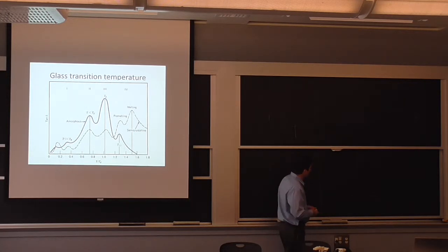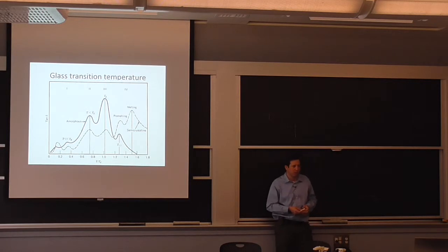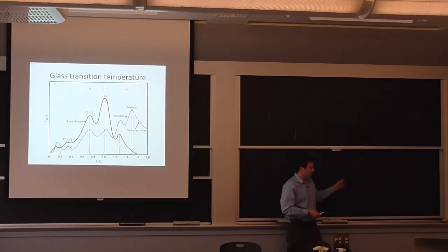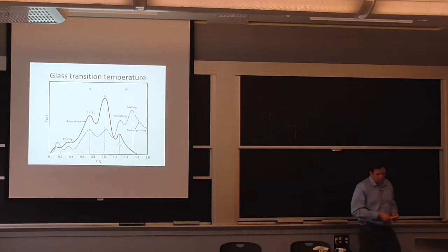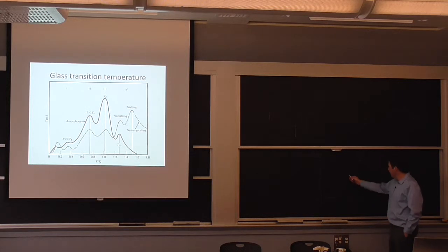And if you have a polymer that will melt at a higher temperature, this point will typically move to the right. So you have PEEK, for example, that's used for relatively structural applications, but more expensive, but it has a higher glass transition temperature. So this process of knowing for a certain temperature how much free volume you have is the intrinsic behavior.